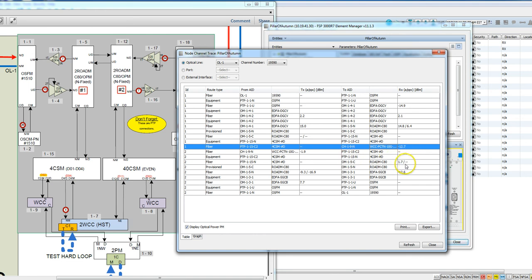And so the ROADM is not really giving us any information there. However, as it goes through that ROADM and is processed, it's telling us that it's now spitting that channel out of that ROADM at a neg 16.9 dB as its power per channel, average being a neg 9.3. So neg 16.9, it's leaving the network interface of that ROADM for that channel.